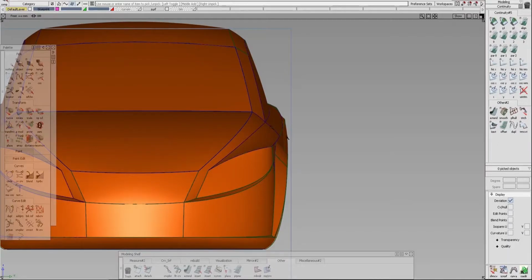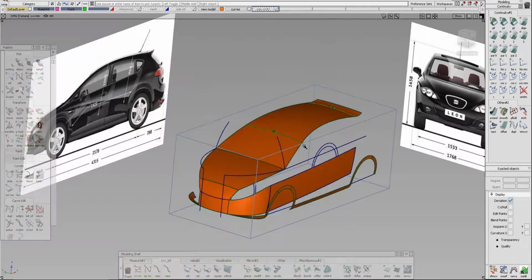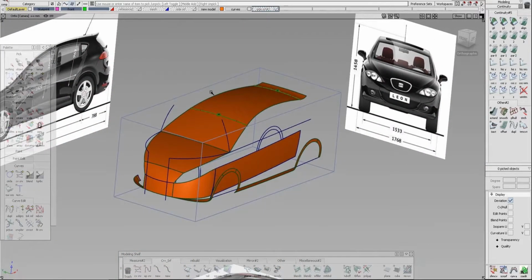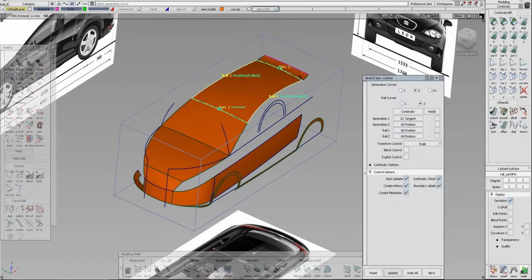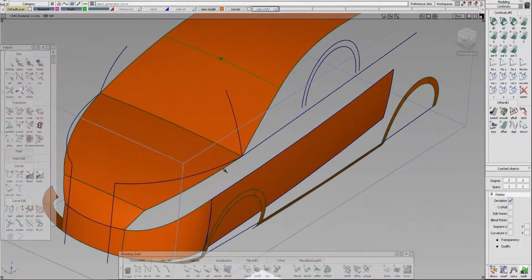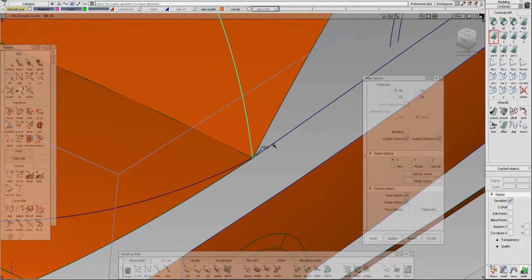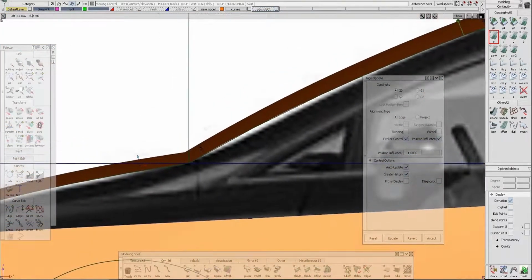Notice the width of the shoulder surface here in my design and in the model we are building. You see how right here it's a lot shorter, so we need to move this point inwards. So that's what we'll do first. So I'm just checking if we have history active on all of our surfaces. And we do, so that is a good start. And then I'm aligning all of the curves with G0 that are touching that point.